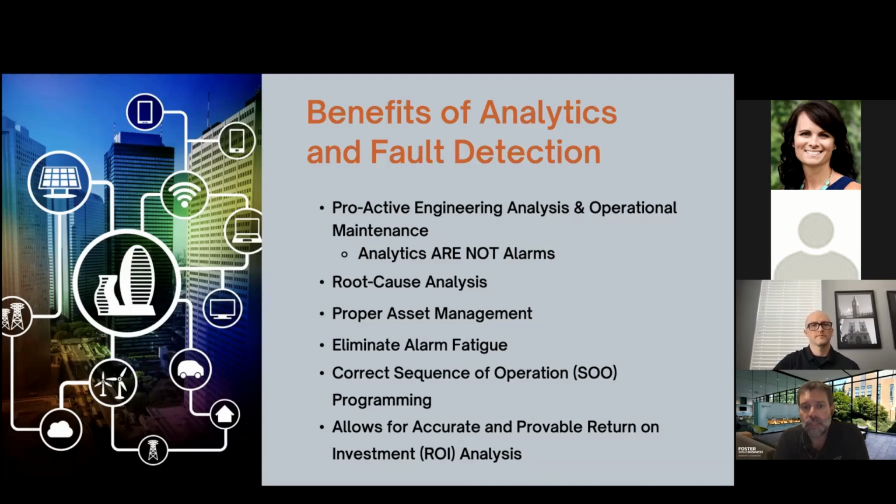But with the fault detection, what it's going to tell you is that you're at full cooling in this situation all the time. And then you can actually get to the root cause of, is that undersized, or is it that the upstream air handler is undersized or at capacity? So getting back to that root cause analysis and being able to look at that and overlay multiple different points and analyze that at one time.